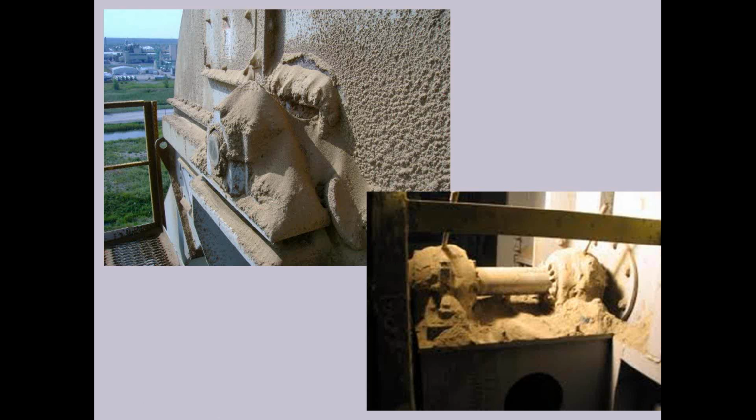So again, and this is what I say when I go around plants, when I look at things like this, these are failure modes. And this is what you want to look at in your operation. We've seen the motors that were completely covered. That's a failure mode. So when we see our lubes dirty, we see grease bearings like this covered. Now there's a grease zerk underneath that pile of dust that a maintenance person has to dig around to put grease in that bearing. Well, in many cases, we pump more dirt particles into the bearing with the lube practice.